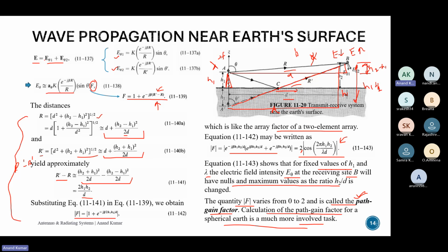We did a lot of math starting from this figure: the expression for electric field at different steps, calculating the difference value for the phase part of the array factor-like term over here, and then the observation from this expression that we will have nulls or maxima if the receiver is moved in distance from the transmitter. So I'll pause over here. If there are any questions on this, we can take them now, from here or the previous slides. Else we can end this meeting.